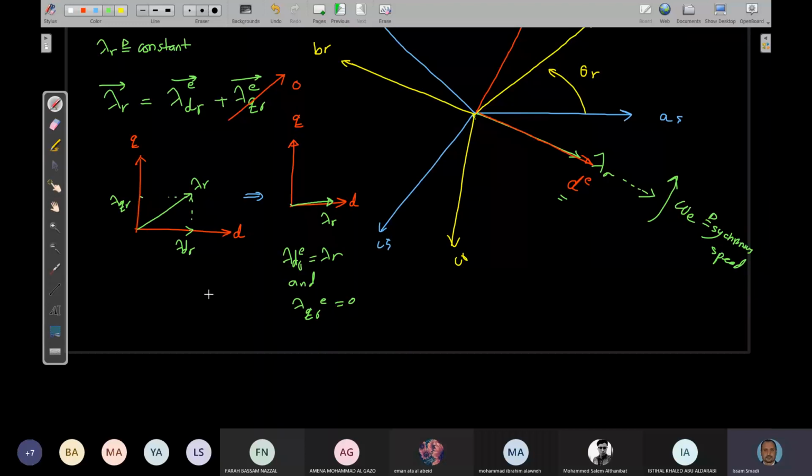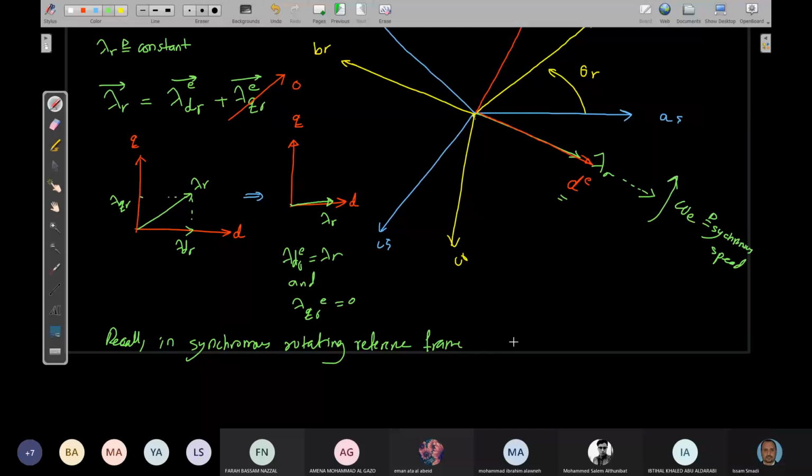And also I need you to remember that in synchronous rotating reference frame, all the sinusoidal signal is seen as a constant. So here I will write or recall for you: in the synchronous rotating reference frame, the sinusoidal function is seen as a constant.